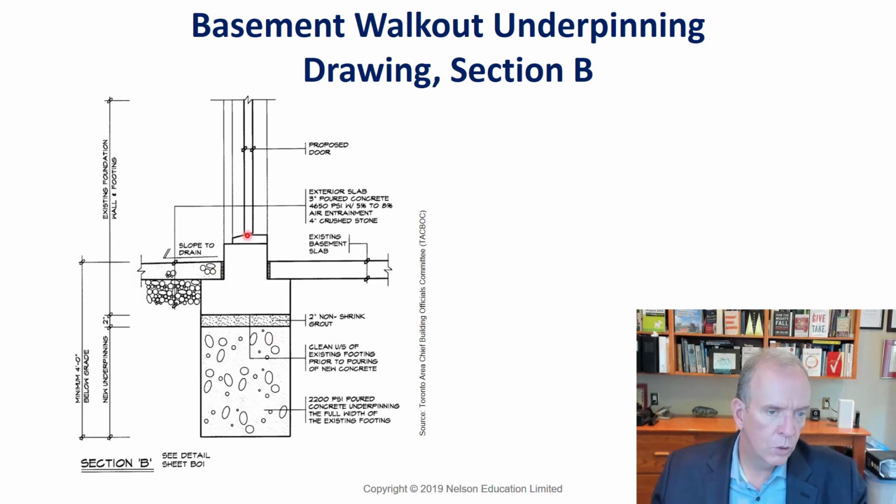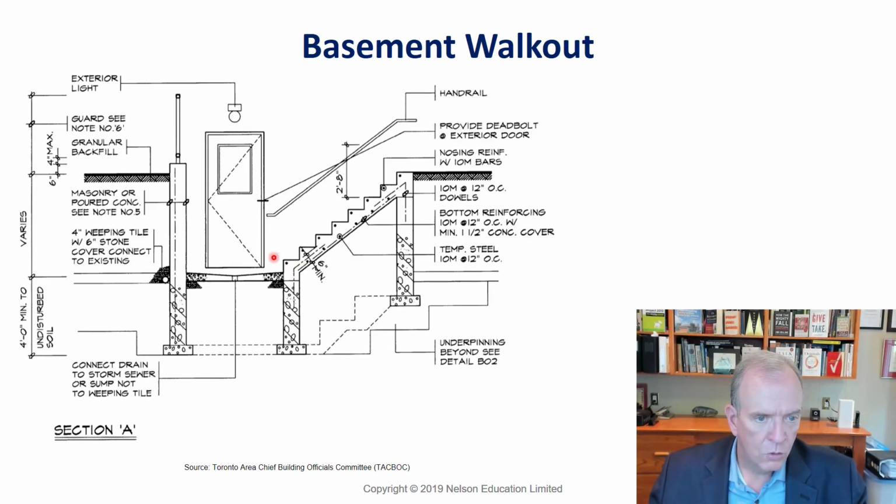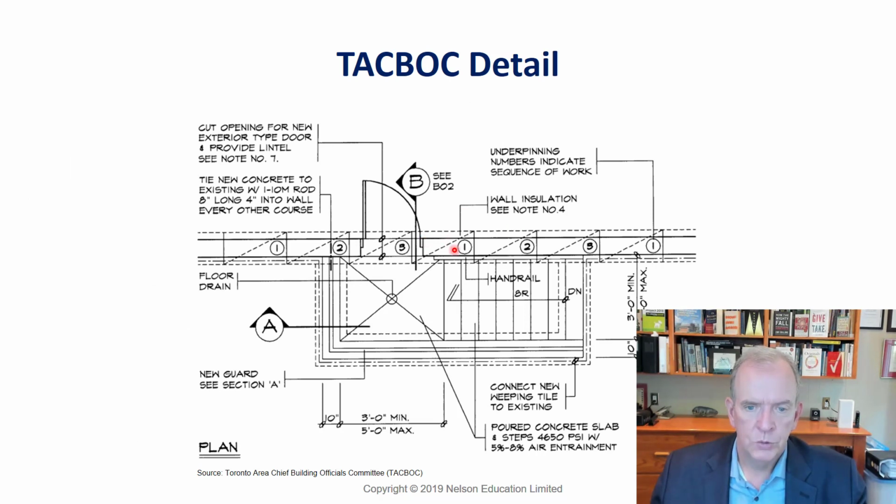And the house where the doorway is, this has to be lowered too, to make sure that the frost doesn't go through here and heave up the area that's all opened up here. So like this would have to be 4 feet down here, this would have to be close to 4 feet, and then it'd be less, right? But 4 feet from any of these points. So it could step up from there, your underpinning, if you wanted it to, till it's that far away. So that's why it's showing this continuing past, and then this continuing this far past, 4 feet from there.